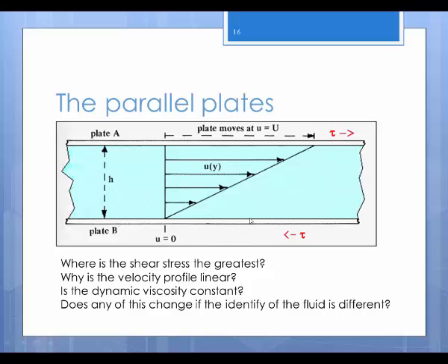And we generally assume that in most fluid problems, which is how, if we knew that this was going to be a linear velocity profile, we would say, I know that this plate is going at 1 meter per second, which means that the fluid at the top is 1 meter per second. I know that this plate at the bottom is going 0 meters per second, which means the fluid here is at 0. So if you knew this distance h, you could get your constant du dy in this situation without taking any measurements at all in the fluid, and you'd know exactly what the shear stress was. And that would be important because you'd know exactly what this force would be, and you'd know how much the resistance to flow is affecting the force it takes to actually move this.